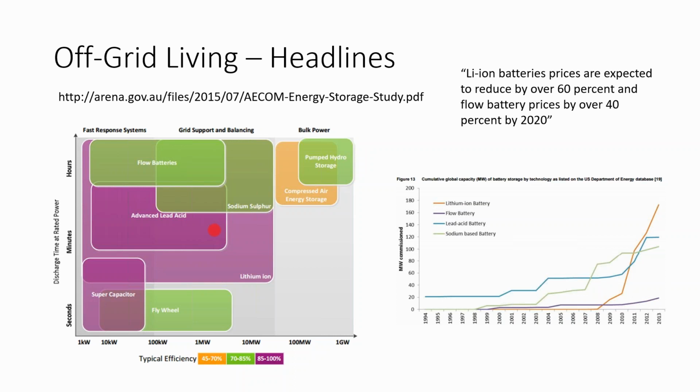Now, is that heat going to burn your building down? Well, that's why you have tremendously thick cables that are appropriately rated for the amperage that's coming out of that battery. So that's more of a function of National Electric Code sizing, where you can see how much amperage is coming out of the battery and you size your cables appropriate to that amperage.